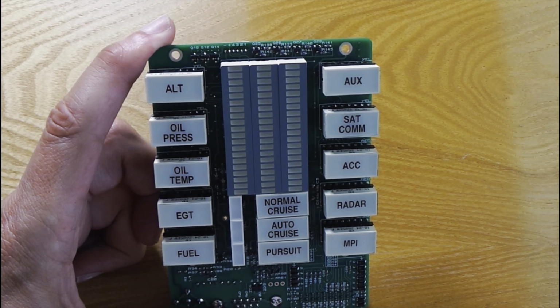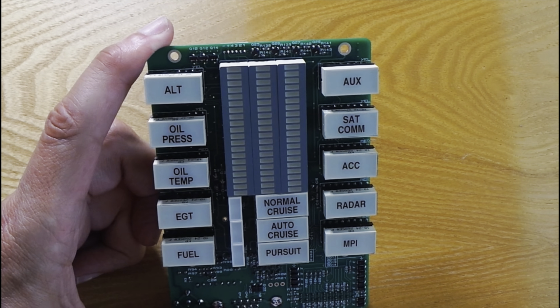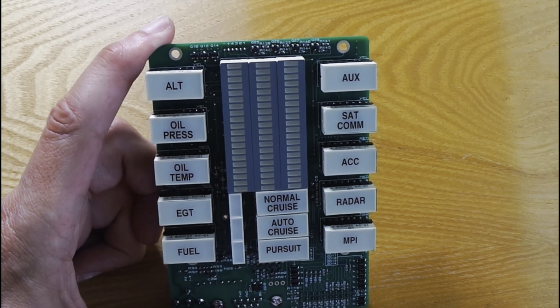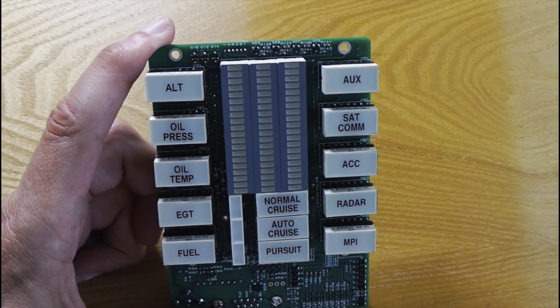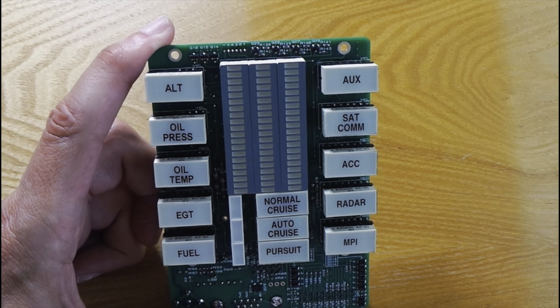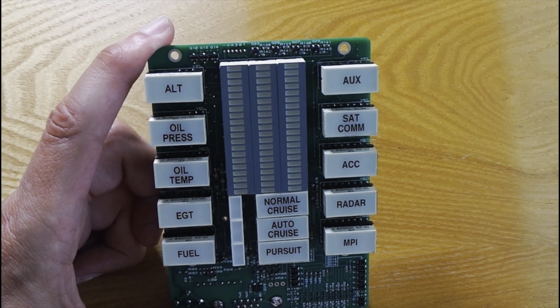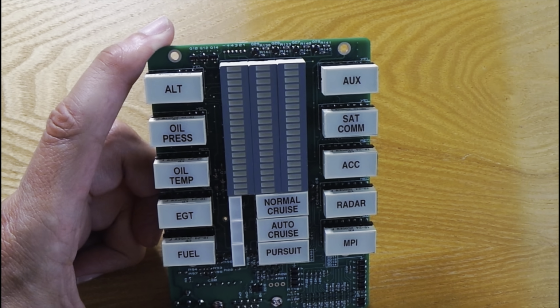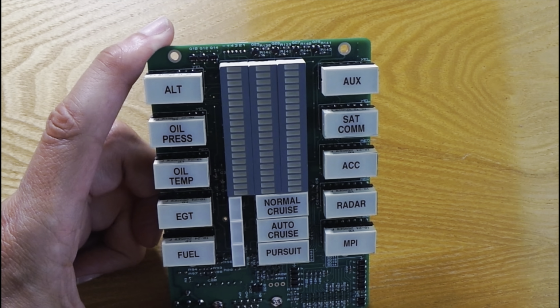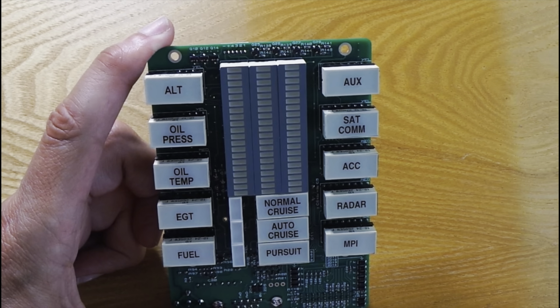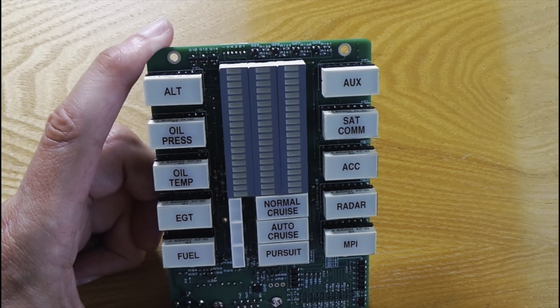The dash-top indicators themselves can be programmed to switch off when the lights are on, that is if you have the lights connection connected, and that's something that has to be set in the programming, so that would have to be reprogrammed if you want to change that. The default setting is that yes, the dash-top indicators do switch off when the lights come on. Another one is that you can program the dash-top indicators to go off when you turn potentiometer number 2 right down to its minimum value. Again, that's something which can only be changed within the programming.